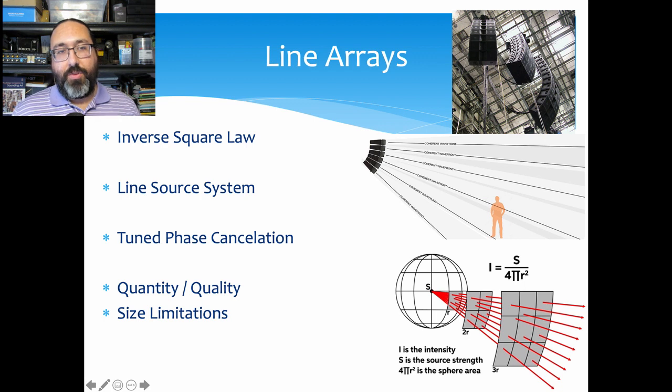The last thing that I want you guys to be aware of, and that is because they've gotten intensely popular lately, are line arrays. Now, line arrays are kind of interesting devices because what it does is it takes a stack of drivers and a bunch of speakers, stacks them all together, uses phase cancellation in a conducive way instead of an unconducive way like we normally think of phase cancellation, to allow you to throw that sound further more evenly over long distances.